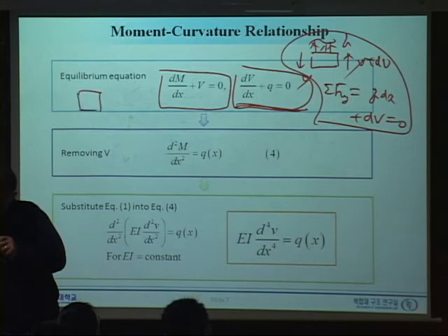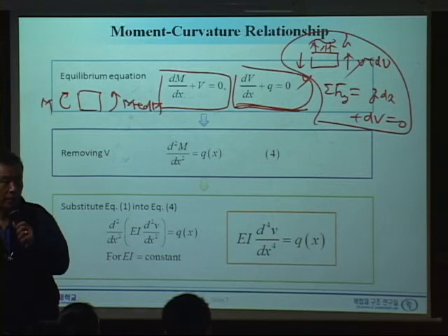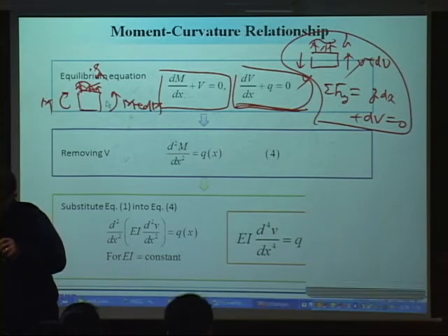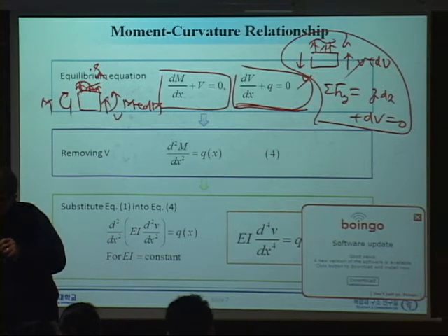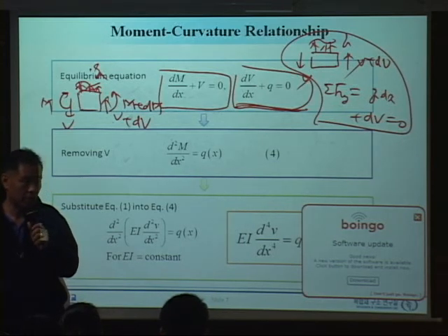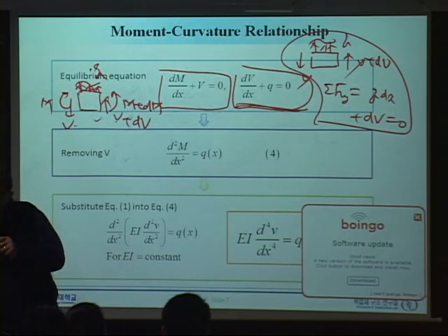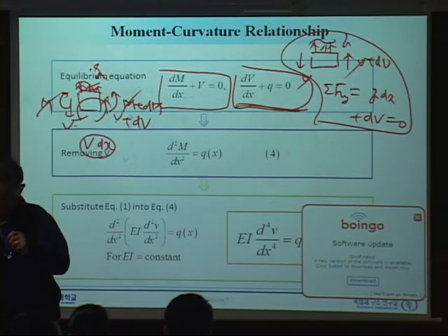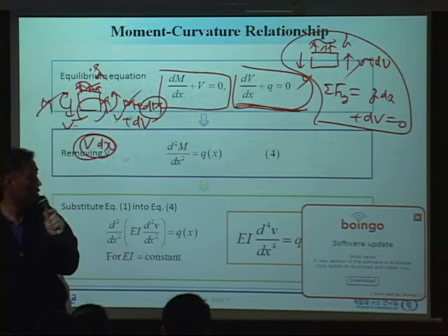And this one, where we have the moment M plus dM and moment M like that, and we have some upward equilibrium, and then we have V here and V here. Actually, we have dV, but dV doesn't contribute to this term. So anyhow, the shear forces V are causing moment, right? V times dx. And M and M disappear. So V times dx should be the same as the incremental moment.